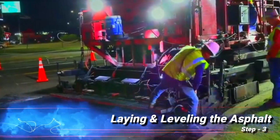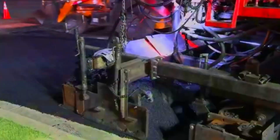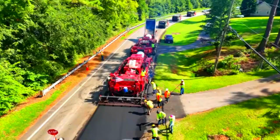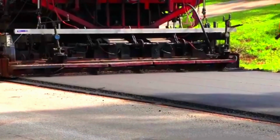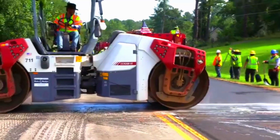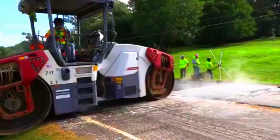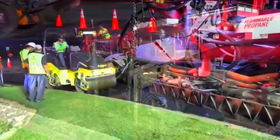Step 3. Laying and leveling the asphalt. After mixing, the heated and rejuvenated asphalt is fed into an asphalt paver. The paver screed evenly spreads and levels the asphalt to achieve the desired thickness and road profile. Automatic grade and slope control systems ensure consistency in thickness, preventing uneven surfaces.